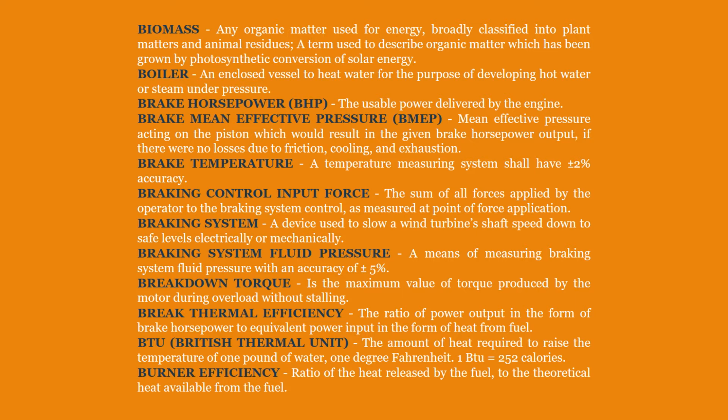Breakdown torque. Is the maximum value of torque produced by the motor during overload without stalling. Brake thermal efficiency. The ratio of power output in the form of brake horsepower to equivalent power input in the form of heat from fuel. BTU, British Thermal Unit. The amount of heat required to raise the temperature of 1 pound of water 1 degree Fahrenheit. 1 BTU equals 252 calories.